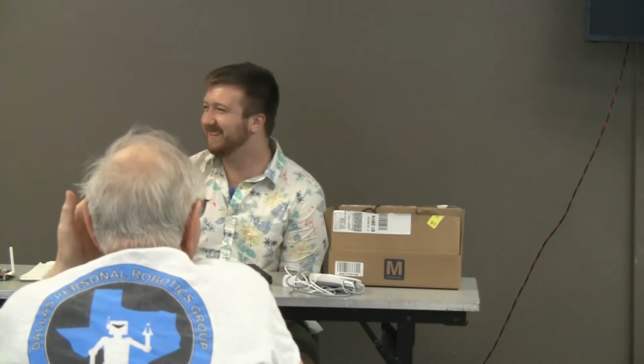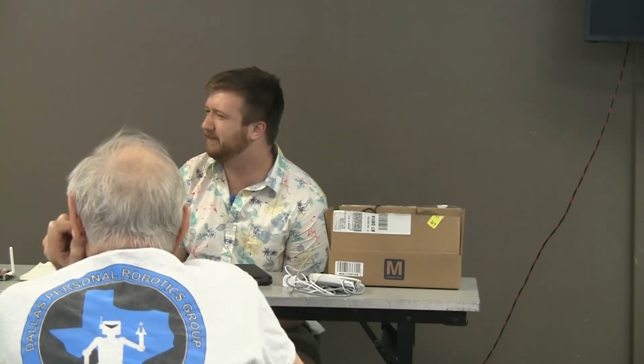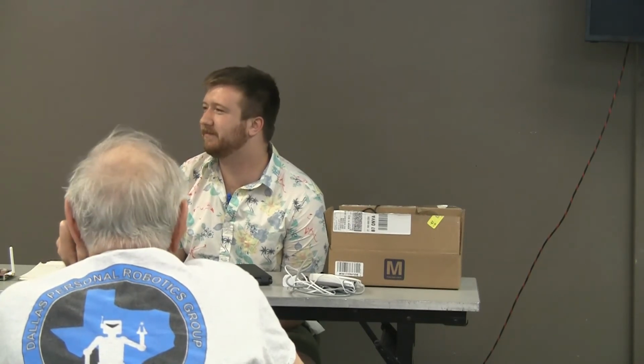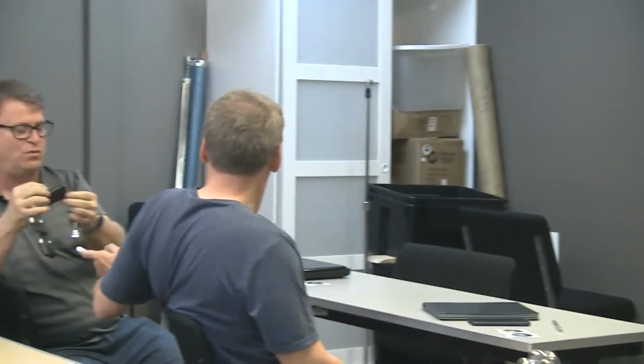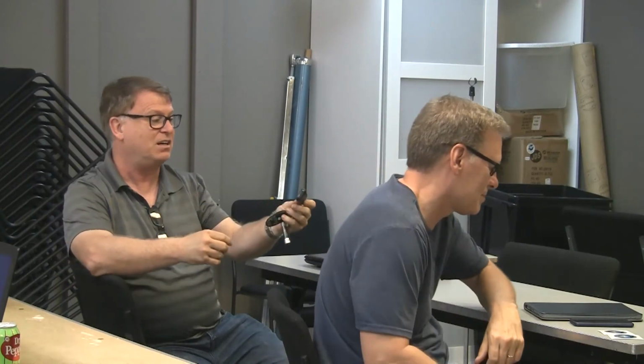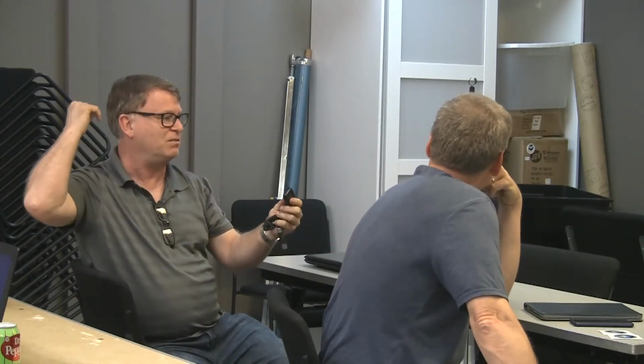I came up with much worse than that. I realized when these things first came out that they have 2 radios in them. They've got a very low frequency 330 kilohertz receiver that's next to your doorknobs, and then they've got a high frequency one, 400 megahertz or 900 megahertz. What you could do is go up to the car and just put a receiver up to it, and then transmit that to the thing inside the person's house, where they're inside the house.